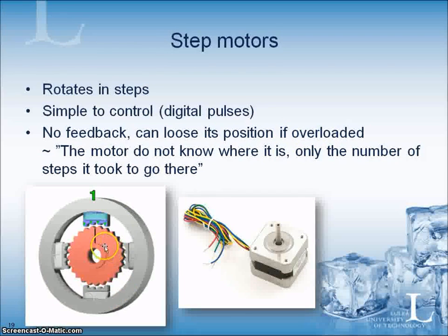Then it can just rotate and get stuck in another position. You can say that the motor really does not know where it is, but it knows exactly the number of steps it took to go there. And this is something you should keep in mind.